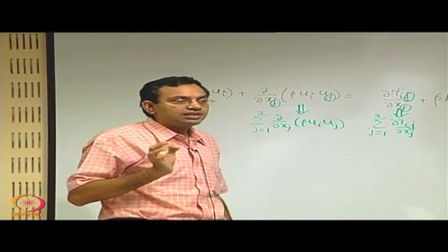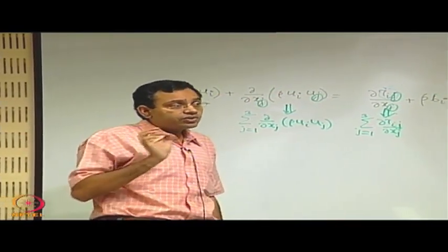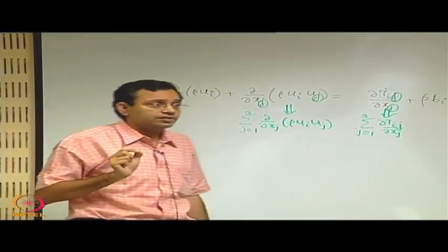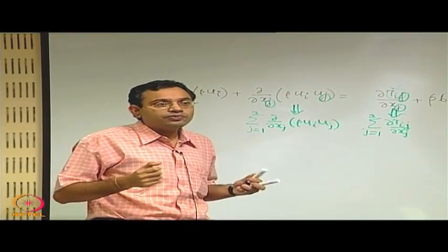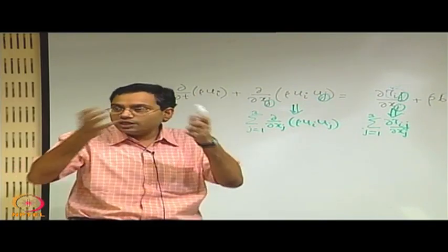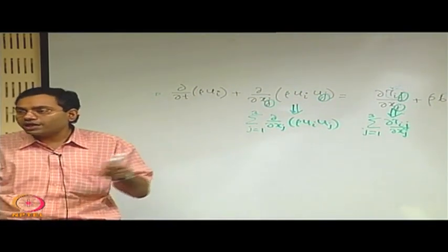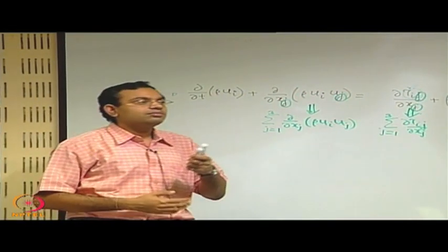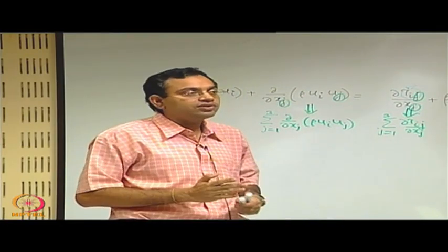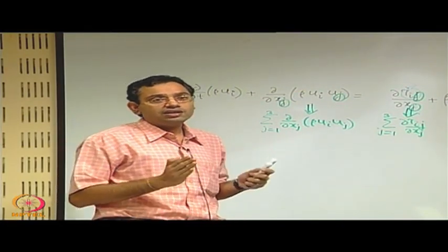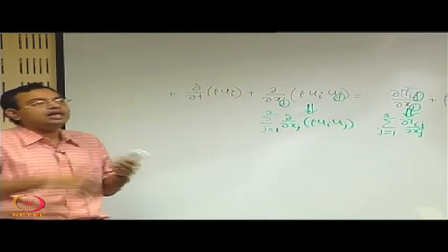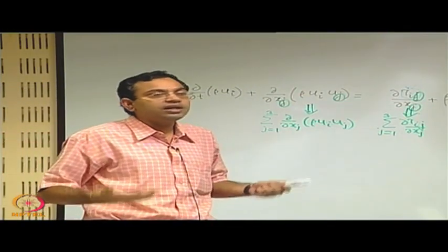So, if it is at rest, that means there is no shear force, there is only normal force, but a special type of normal force that is not dependent on deformation, because you can also have a normal force which may be related to deformation, not angular deformation, but volumetric deformation. If you have an element, you may be able to stretch it or compress it by a normal force. So, it is not simply true that a normal force is not related to deformation. Normal force also may be related to deformation, but pressure is going to be such a normal force which is not related to the deformation, because it is equally applicable for fluids at rest which are not under deformation.